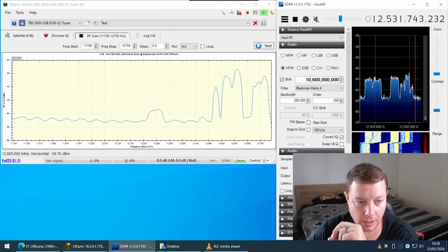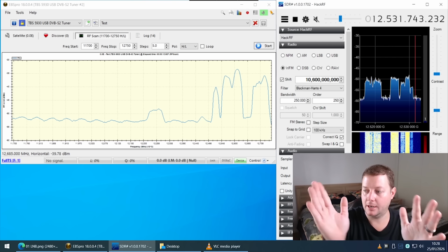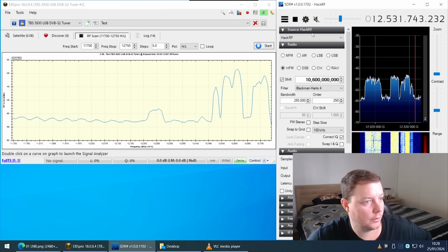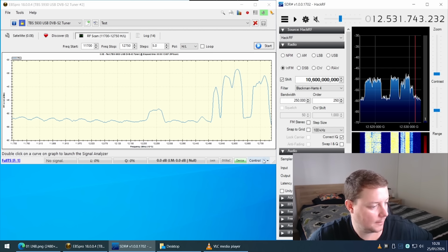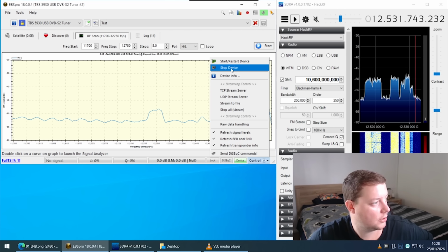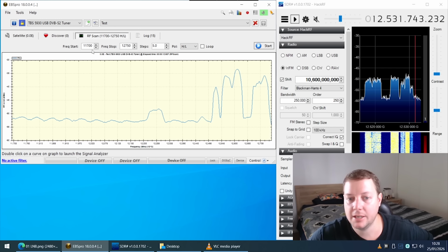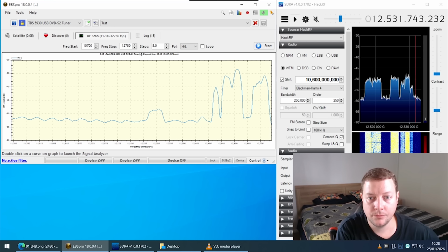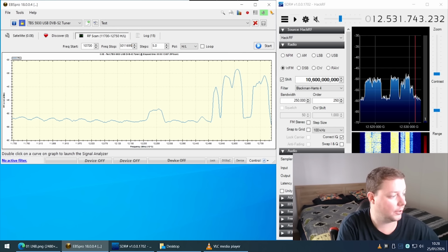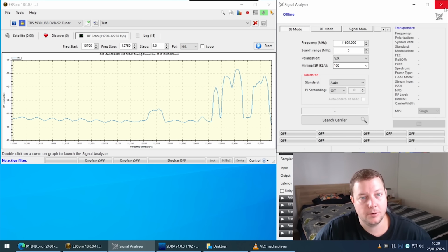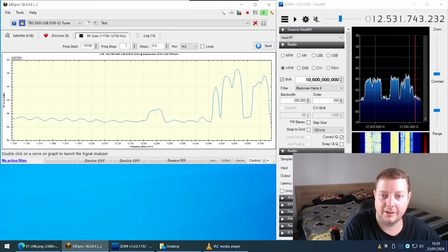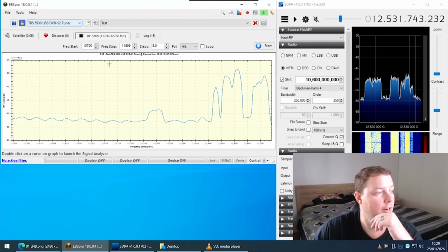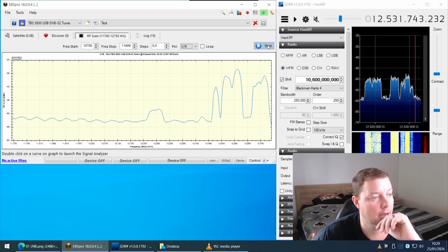All right, let's do vertical, and then let's do the low side mixing now, just for demonstration purposes. So I'm going to stop the SDR. I'm just going to stop my tuner for a second. I'm going to go to the RF scan tab again. I'm going to put 10700 to 11.699. Whoops, sorry. Whoa, what's going on here? Sorry, can't use Control A. 11.699. And I'm going to change my polarization to vertical. And then I'm going to press start.